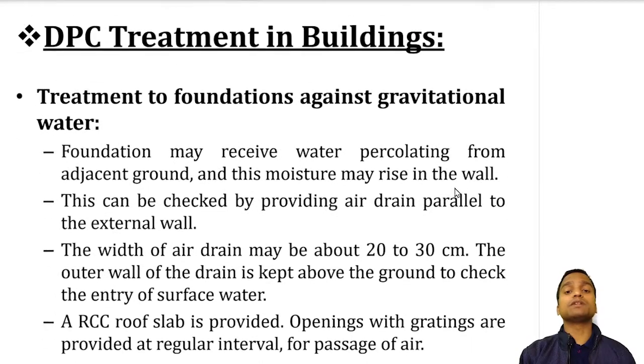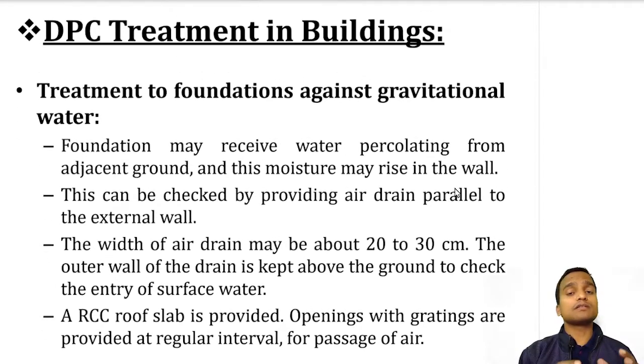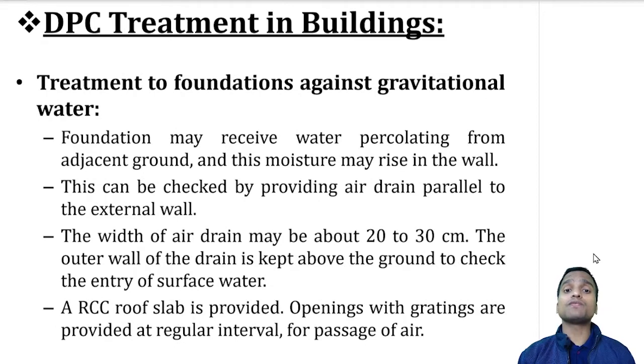Now is the DPC treatment in buildings. See, in buildings there are different elements like foundation, and then there are walls or floors. So all these things have to be treated to prevent dampness. So let us discuss the treatment to foundations against gravitational water which is going through the drains.